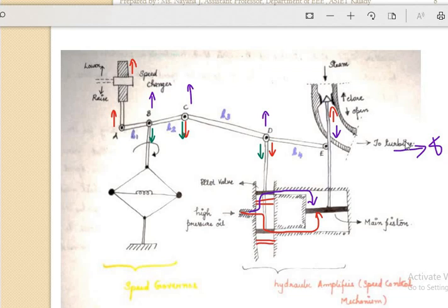In today's lecture we have discussed the need for automatic generation control, and how the active power P and the reactive power Q affect the frequency and the voltage. The active power mainly depends upon the frequency and the reactive power mainly depends upon the voltage. For controlling active power we need frequency control, for controlling reactive power we need voltage control. Together, frequency control and voltage control are called automatic generation control. In this lecture we discussed load frequency control, considering a single area network, and in that the turbine speed governing system.